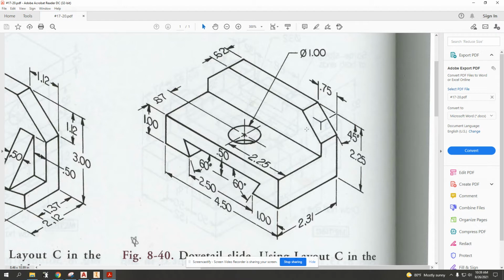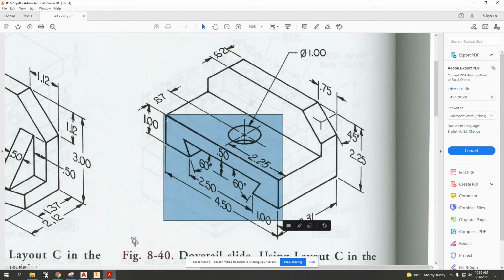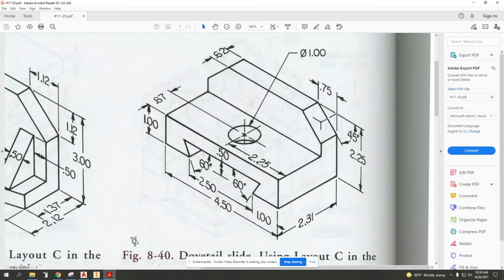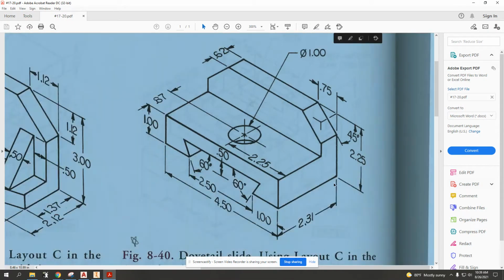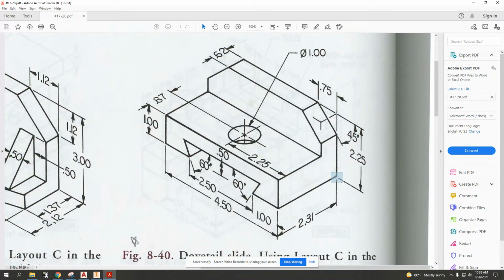There are a number of different ways we can go about trying to create this object in Inventor. You might focus on this front corner, this kind of shape in here, and we can then do some commands called extrude, where we sketch this front shape, we give it some sizes, and then we create the thickness of the object. Another one might be you do this whole back surface from the ground here, the top corner here. And then maybe we make that shape and dimension it and extrude for the entire thickness again.